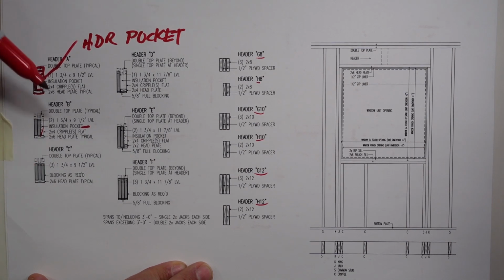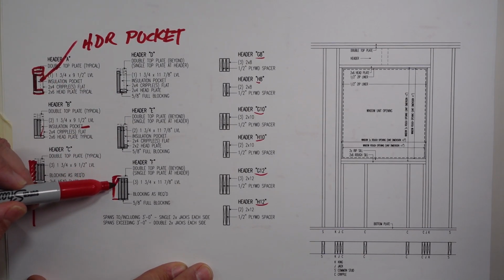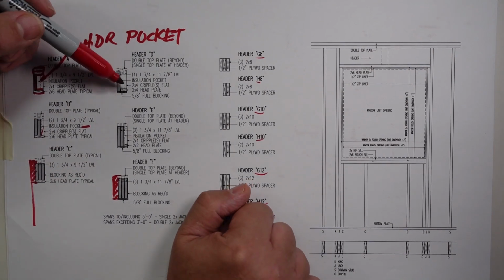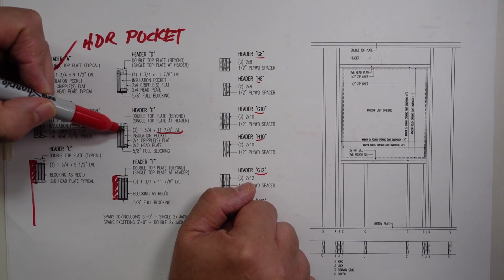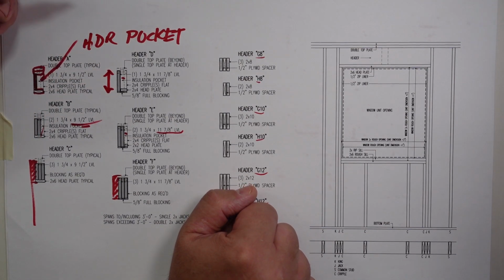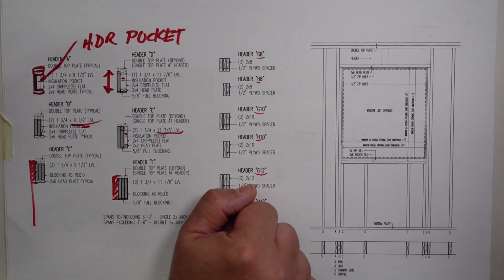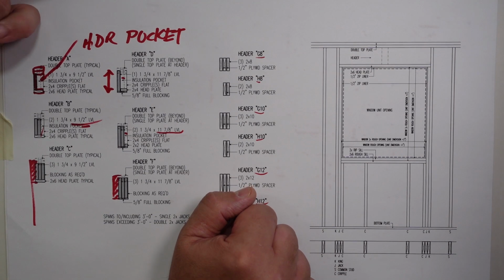Header C, obviously, when we pack the wall with a header because it's a large lift and slide door or something, there's not a whole lot we can do. The hope is that we also have some additional insulating sheathing on the outside that can assist in those conditions there. And you can see here, these are just moving up from the 9.5-inch to the 11 7/8, but the same pockets exist there. The header just increases in dimension and allows us to have a much stronger header. So if we're at a place where we need it or want to push the head height down, whatever the case is, we can make that happen.